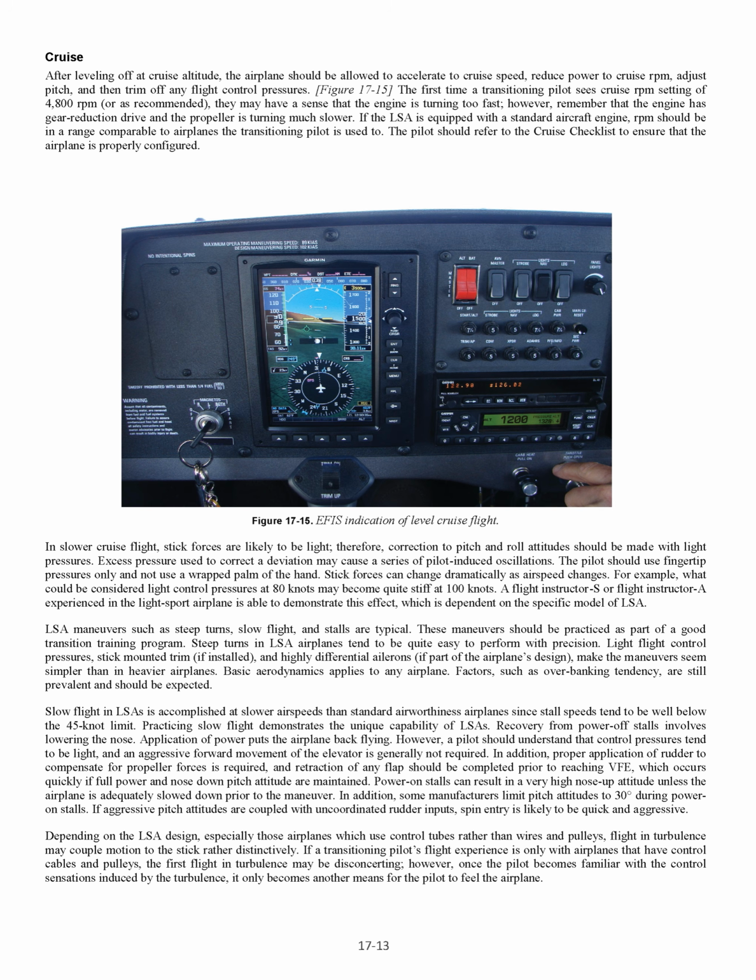LSA maneuvers such as steep turns, slow flight, and stalls are typical. These maneuvers should be practiced as part of a good transition training program. Steep turns in LSA airplanes tend to be quite easy to perform with precision. Light flight control pressures, stick-mounted trim, if installed, and highly differential ailerons, if part of the airplane's design, make the maneuver seem simpler than in heavier airplanes. Basic aerodynamics applies to any airplane. Factors, such as overbanking tendency, are still prevalent and should be expected.